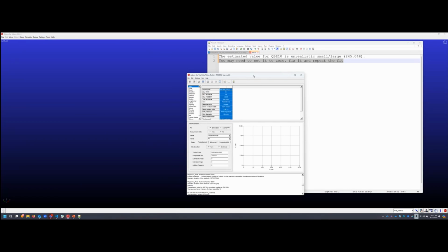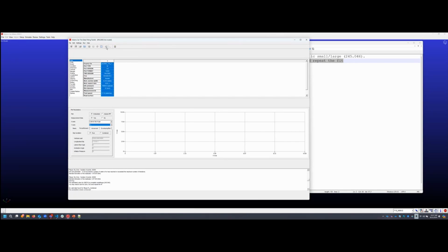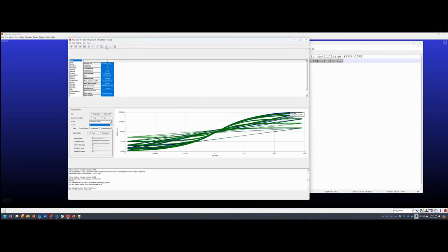Now that I've done the fitting, I obviously want to know if it was done properly, or if the output is going to be similar at least to the input. So what you can do is say yes to the measurement data option, and we did only cornering data, so we're going to only do lateral slip versus, let's say, the cornering force. And I'm going to plot it, which is done by this button up here. If I say plot, as you can see, the green and the blue are pretty decently overlapped, which means you do have a good fit here.